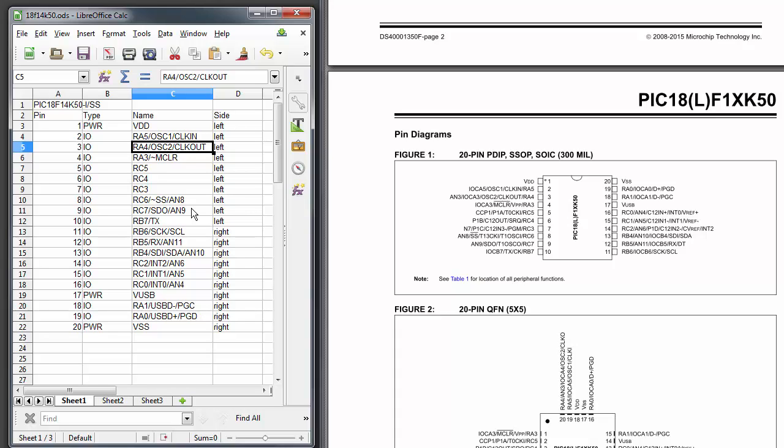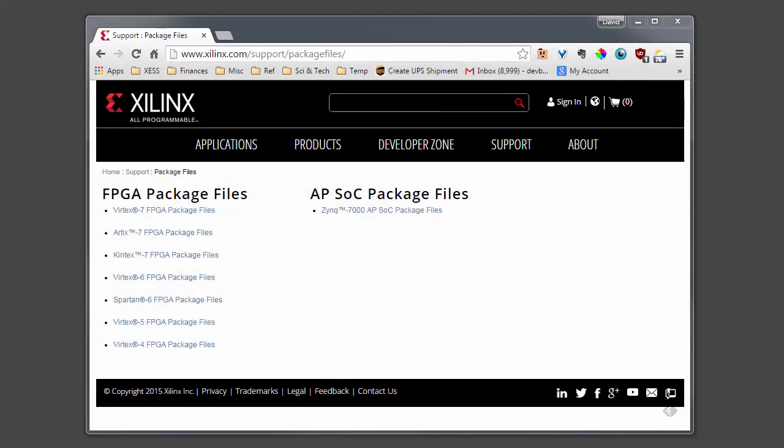And I'd still rather do that than go through the KiCad symbol editor's dialog menu for each pin. Now, the place you really win big when using KiPart is for those semiconductor manufacturers that provide all of their chip I/O information in CSV files or in some text file format, like Xilinx.